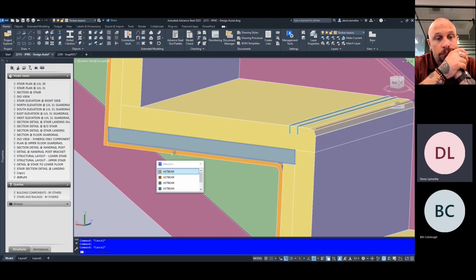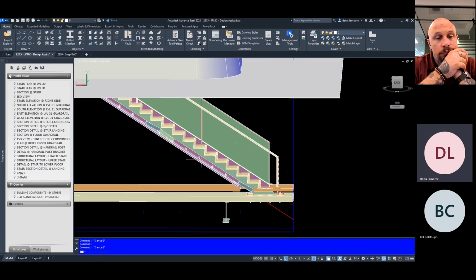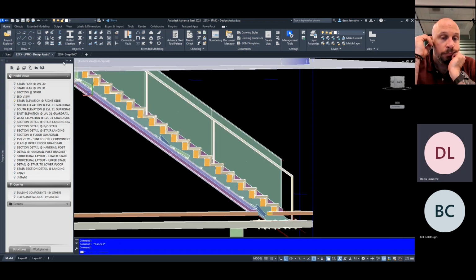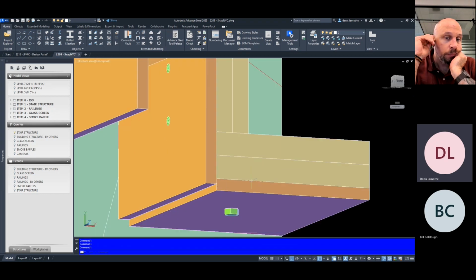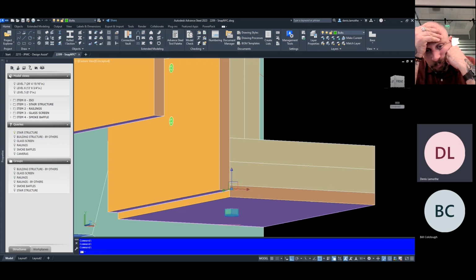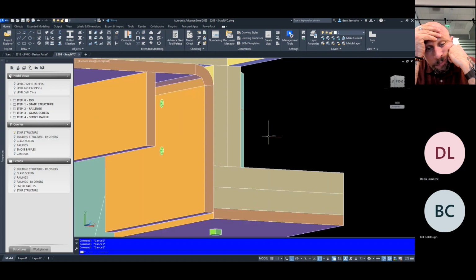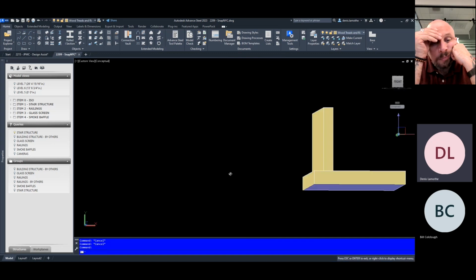And so the plywood would often be fastened. Do I have that in this model? No, not this one. Maybe this one. You can see here where they wanted to bolt. Well, we used excessive live bolts in this one, but smaller wood screws or others would be used to attach the plywood backer to our tread and riser plates. That provided a nice wood finish for them to bond their finished stair materials to.